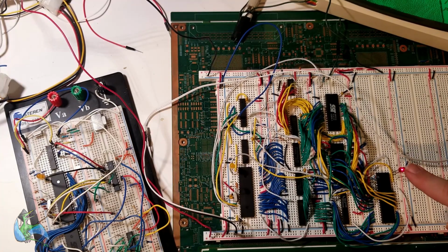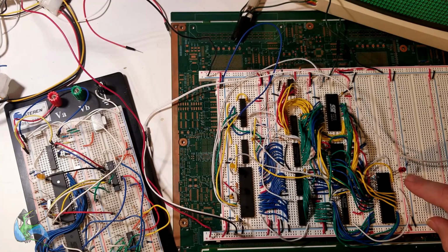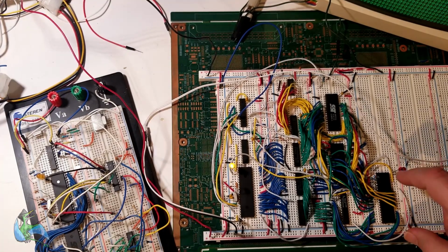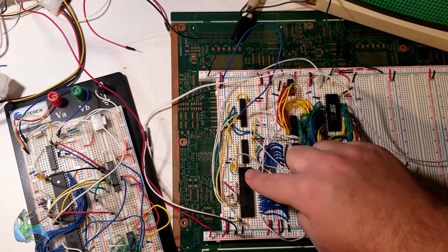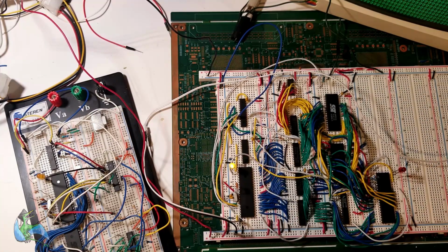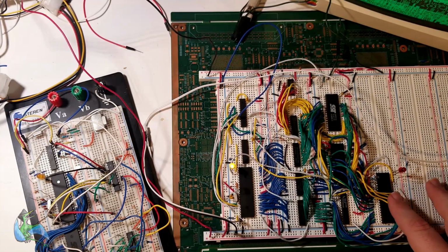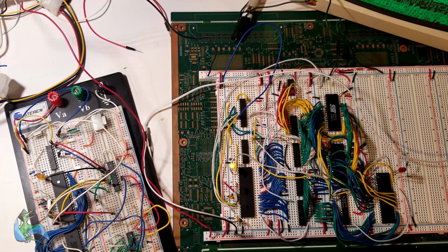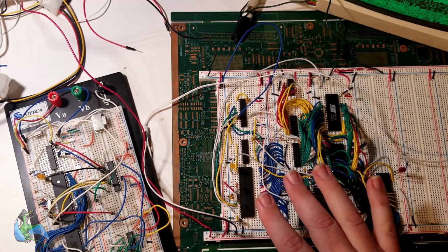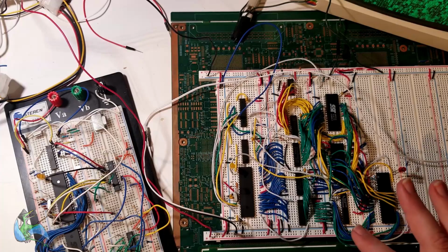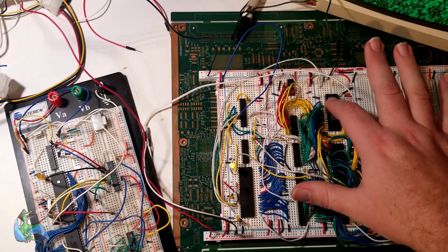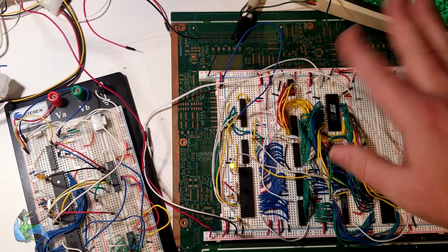Now, see this red light right here? That red light just went off. When that red light goes off, the CPU is running. There's a reset line which is controlled by the MCU right here, and the CPU is held in reset during all those earlier demos. That reset line is also connected to the memory mapper chip right here. So when reset is held high, the ROM chip is the only thing that gets selected out of all of memory. So there's room for those pictures.